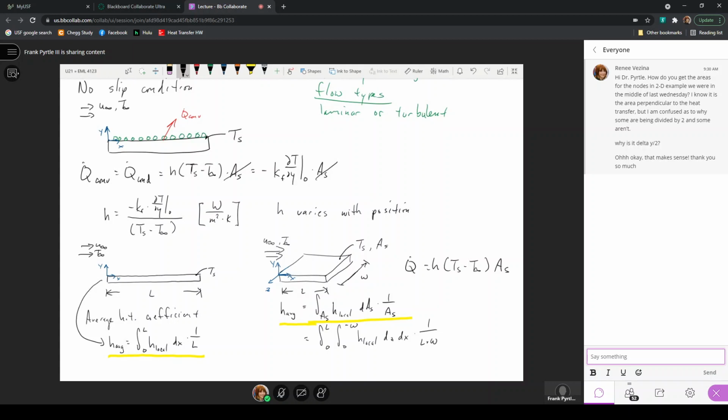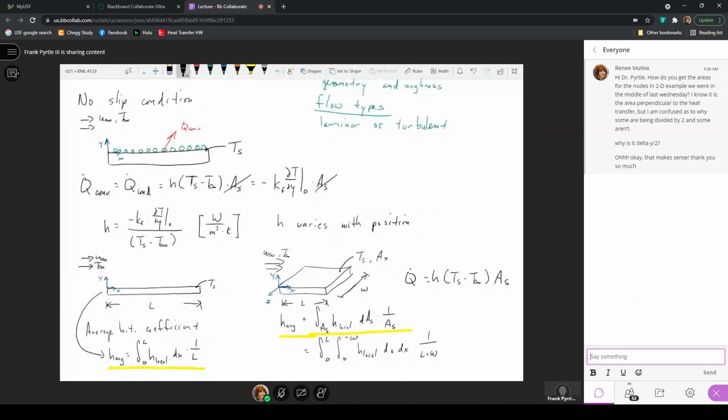So when we're talking about an expression of a heat transfer coefficient, it's always with consideration that the heat transfer coefficient varies with position. And you would have to imagine that that would be so, because if I have fluid moving over this surface and heat is being transferred into the fluid, well, that actually slightly changes the temperature of the fluid so that it's picking up heat as it's moving along the length. Now, it won't change the free stream temperature, but if you imagine a layer over this surface where the temperature is changing, that's what we call a thermal boundary layer.